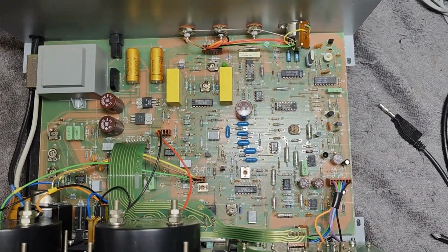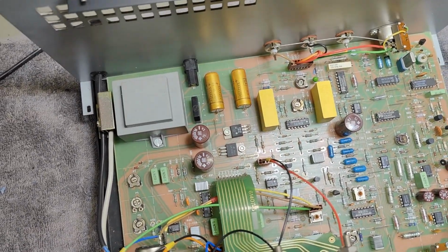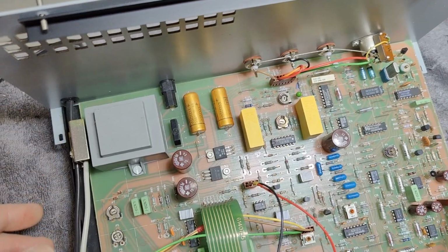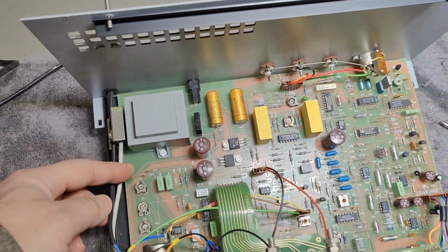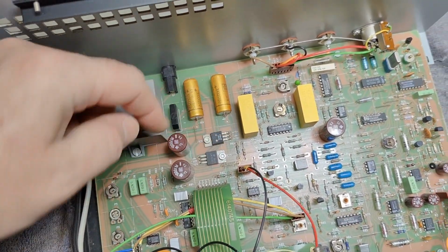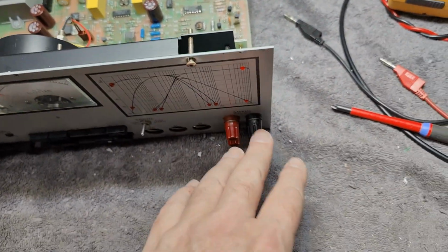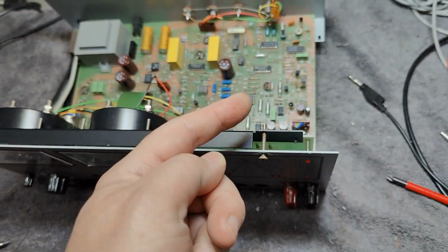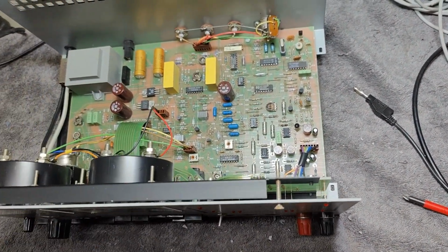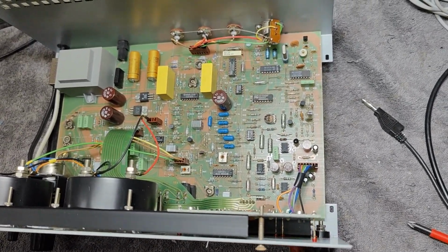And this is the top side of the circuit board. It is just nice and fine for a single layer design. Really amazing. They've done a good job here. And as you can imagine, mains, transformer, rectifier, capacitors and power supply are kept in the far corner, and then inputs, outputs, connectors in the other corner, so the distance between those two parts is the most possible. And that is a good way to think. And these guys, they know how to deal with stuff like that.